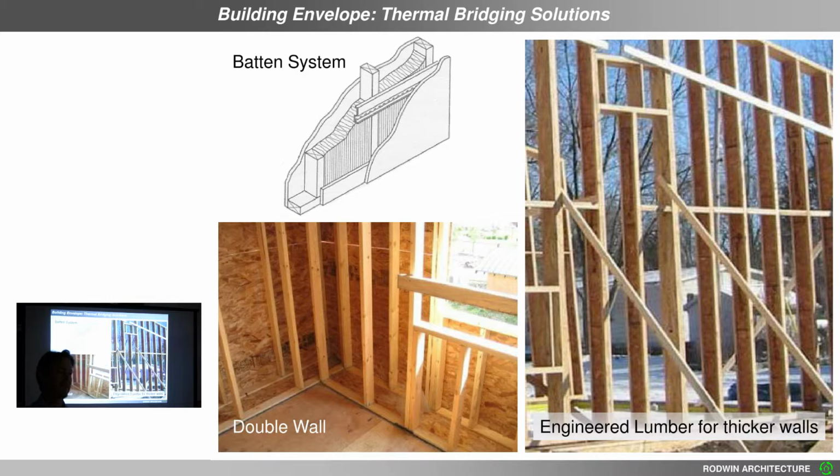On the double wall thing, I always thought they staggered the studs. That is one way to do it. So this way is two walls actually set apart, but in a less expensive way to do the same thing, a clever way is you take a 2x6 base plate and then you have a 2x4 and a 2x4 and you don't align them, you stagger them just a little bit and it creates a continuous 6-inch wide cavity in between.